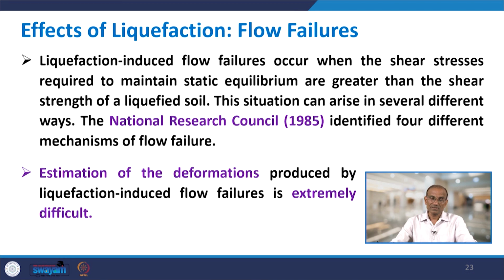So, here, effects of liquefaction, next is flow failures. What happens in flow failures, and then you have cyclic mobility also. So, let us discuss first the flow failures. Liquefaction induced flow failures occur when the shear stress required to maintain stable equilibrium is greater than the shear strength of the liquefied soil. So, this thing we already discussed many times, that for flow failures one of the conditions is that shear stress must exceed shear strength.